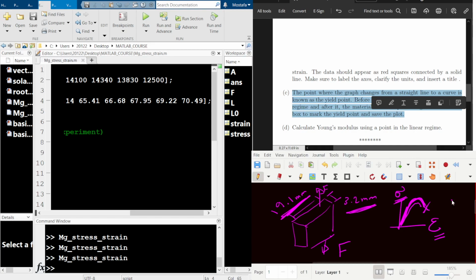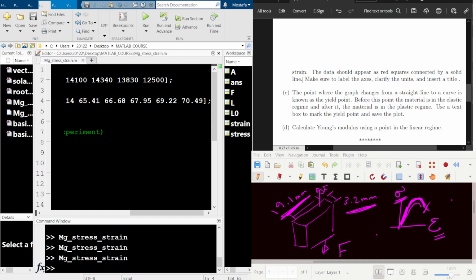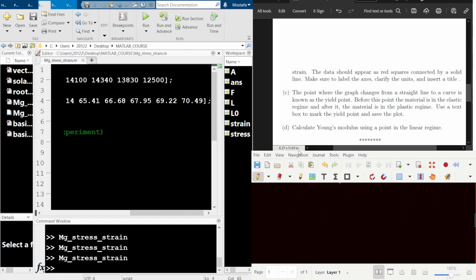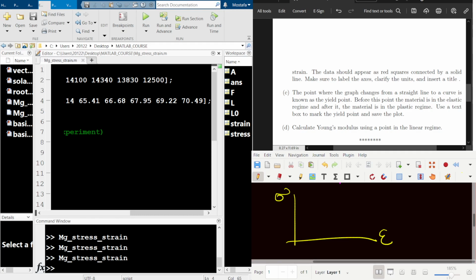So let's see, just to recap what is stated in this question. We can actually move down here. So it's what we said at some point earlier, that a typical stress strain behavior under tensile test looks like this. So there is an elastic regime, and it's usually linear, and then after that there is a plastic regime. Let's denote this with another color. And eventually the sample breaks at the end. So at the end of the experiment, it breaks.